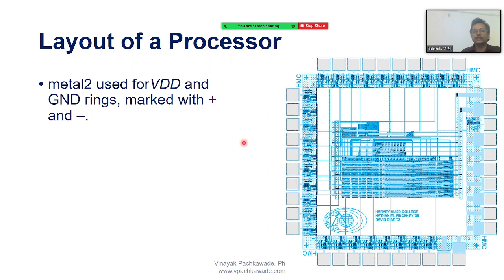so now you see here metal 2. I said that out of these 40 pads, 10 on each side, I want to use few of them for the signals. You see that signals, like these are the metal wires, they are all connecting to the pads through these connections, right? These are the metal wires here, and I am using few of them for VDD and the ground.